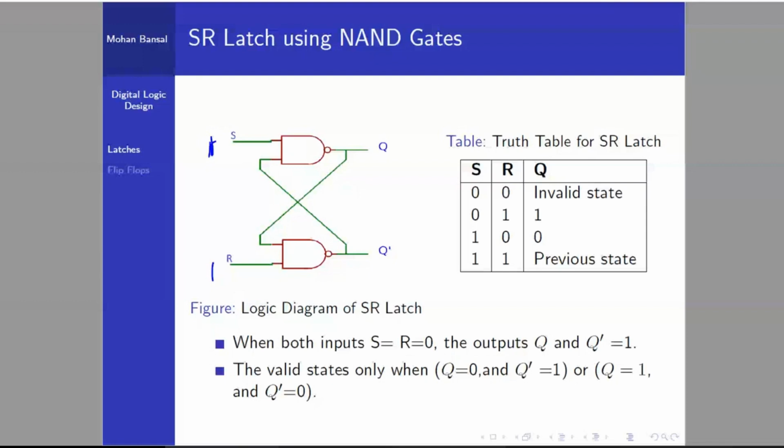Here if we consider 1, we will get 0. Same here. So we don't know what the input is at this point. What should we consider here? We know only 1, but if one input of a NAND gate is 1, we can't conclude what the output will be, because if the other input is 1, it will become 0. So what can we do?